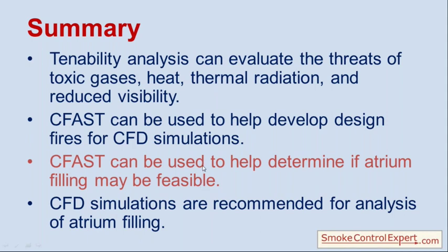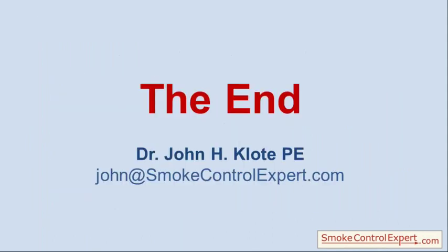It can tell you that if that was your design fire on that earlier table, and you had the 30 meter cubic one, that tells you that it's definitely not worth wasting your time on doing a CFD analysis to design the thing. But CFD simulations along with tenability analysis are recommended for atrium smoke filling systems.